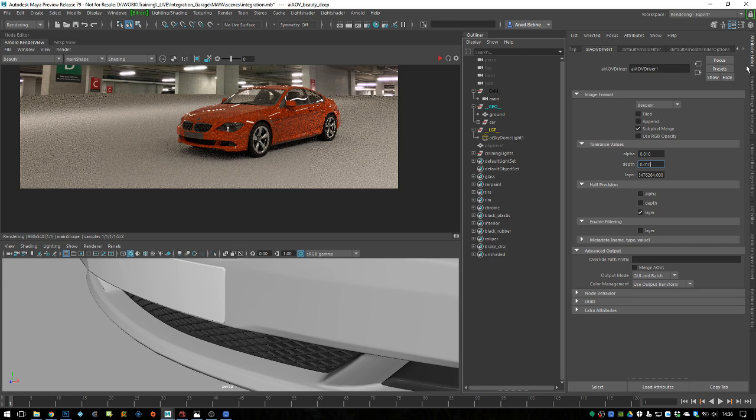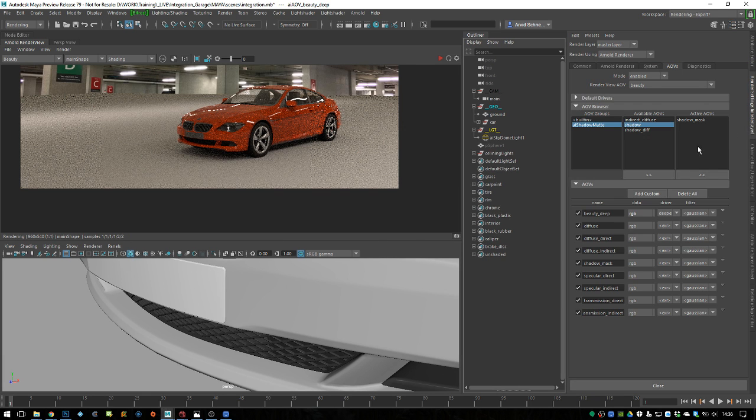So this would only render deep. This would render deep RGB, which in most cases you don't need. You just need the deep information, so you can actually render deep alpha only, and you do that in the render settings. So you can just change this to be float. So you render deep EXR as a float, which is a single pass, and this should output deep alpha channel, and that you can then use in Nuke to recolor.